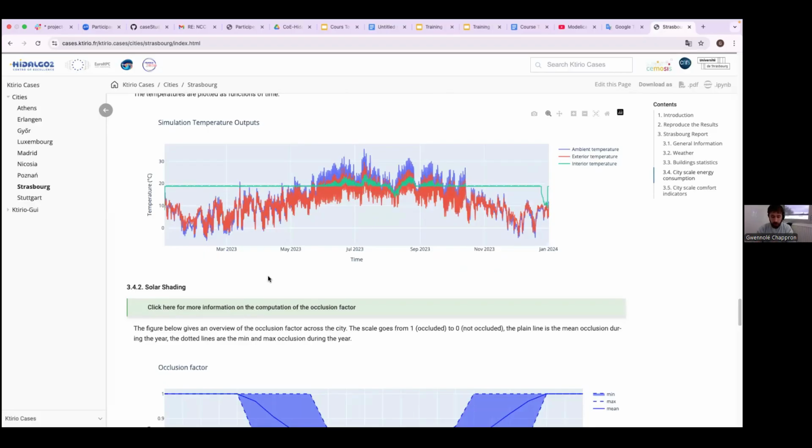So in ParaView, it's not very easy to visualize correctly the temperature inside the buildings since they are changing over time. But by displaying it as aggregated data over the years for the entire city, we can check if we model correctly the different scenarios for heating and for cooling. So as we have seen previously, this is a weather data file that is correct for the northern hemisphere.